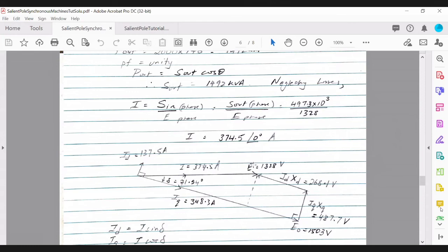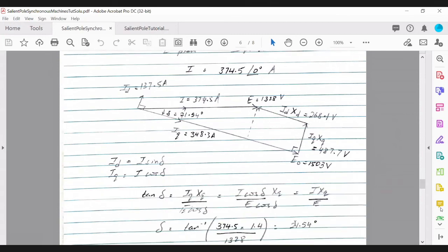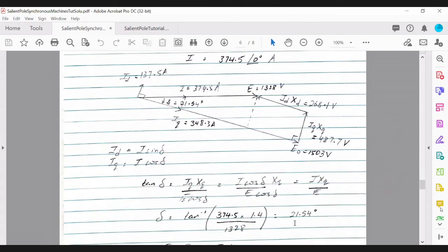So for us to solve for the induced voltage, you will need to take, again, E cos of delta, which will be up to this point, and then you add I dxt here, right? So that's what I've done. Firstly, I've written the equation for your angle.